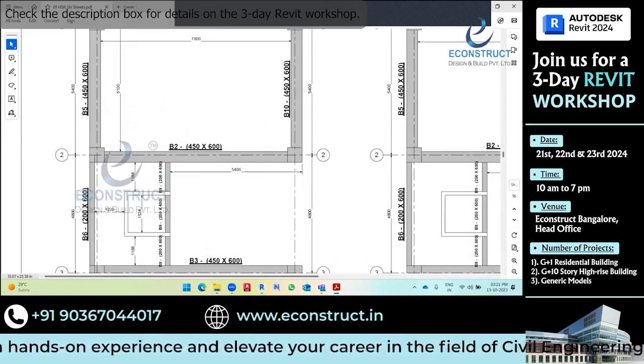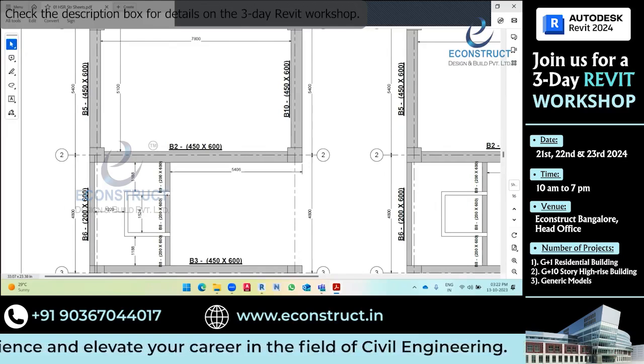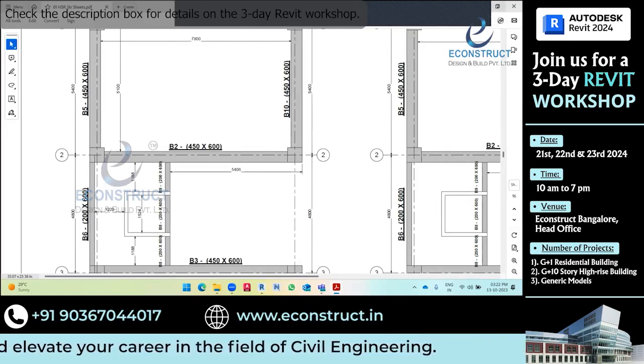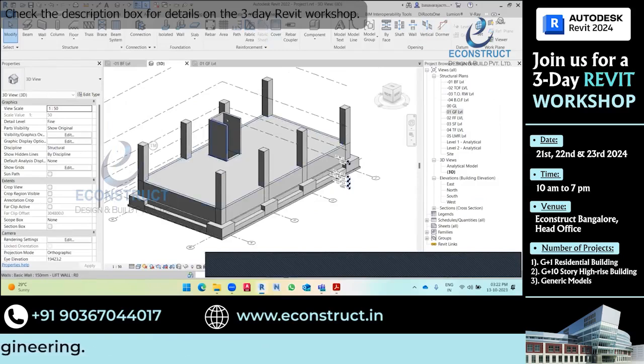So from this internal surface of the lift well, it should go 200 mm. So what we have modeled is correct, means this is 200 mm, right? So this is correct. Like this, you need to model. Go to 3D view. The lift wall is ready now.